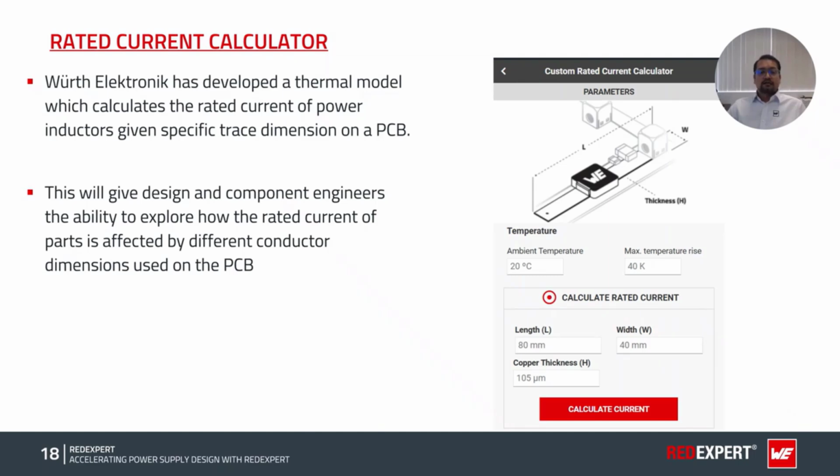And this is important because thermal performance of an inductor is not just about the component itself, it's also about how heat is transferred to and from the PCB via the copper traces. This gives component and design engineers the ability to understand exactly how their layout decisions affect the current carrying capability of the inductor they have selected. It removes guesswork and helps you design with confidence.